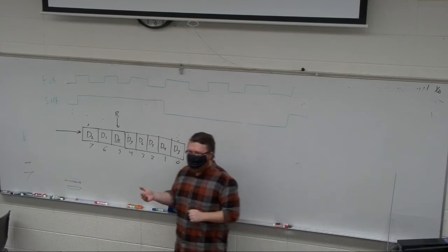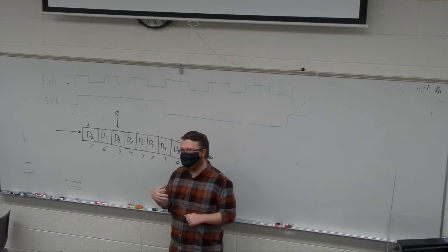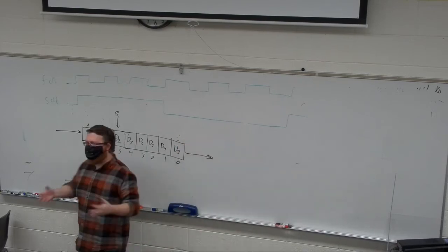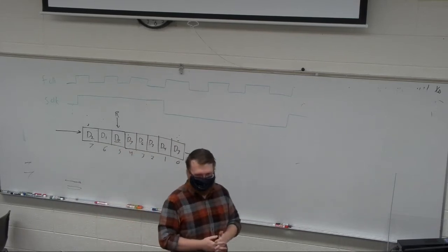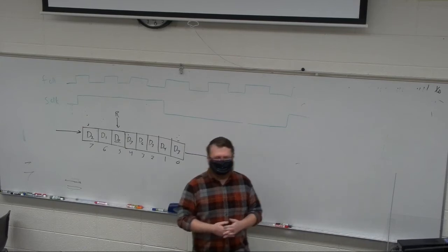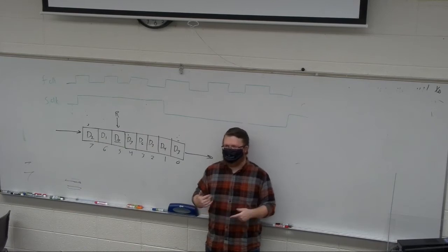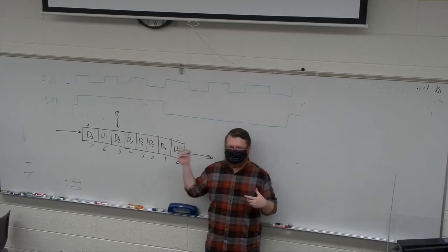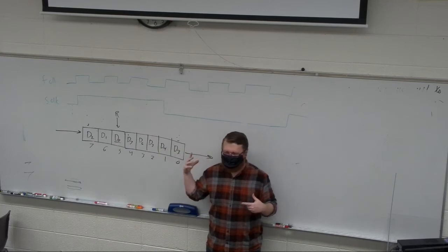But to implement this asynchronous FIFO, you can have, well, issues. The way I would strongly recommend implementing an asynchronous FIFO is to use an IP core, right? So just like a memory, they will have a FIFO. You'll be able to tell. So another way of saying asynchronous, you'll also see it called dual clock, because you'll have an input clock and an output clock. And they'll implement some of the ideas like slowing the data rate and that kind of thing.